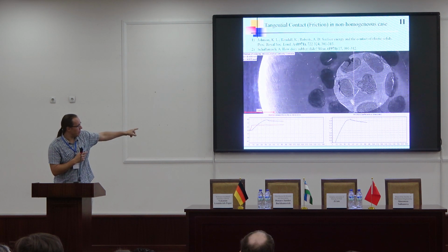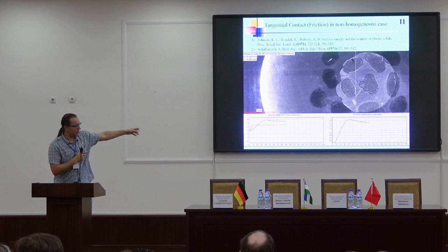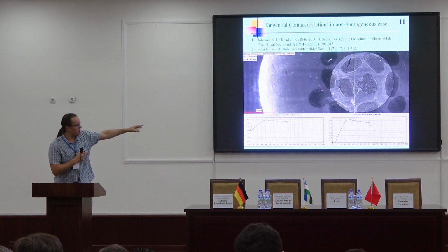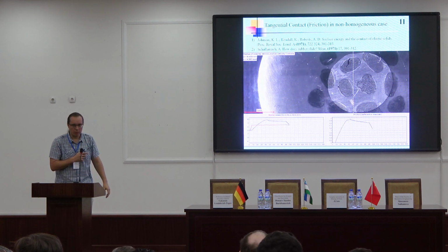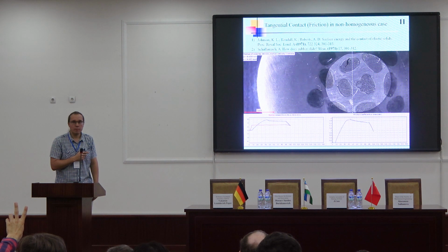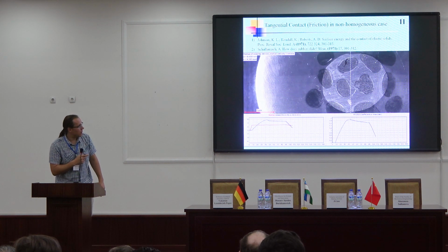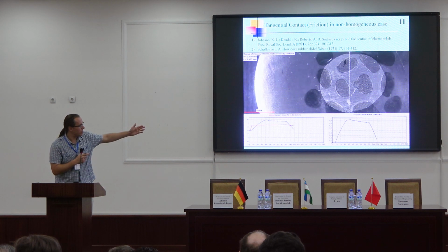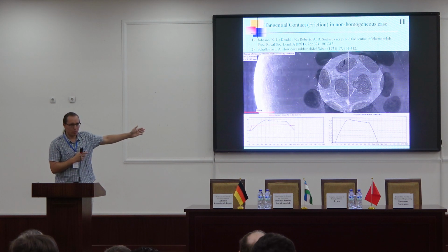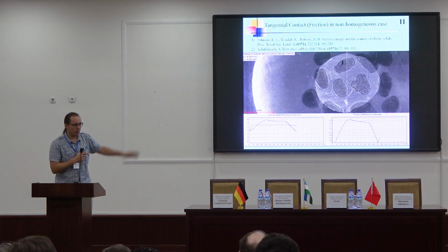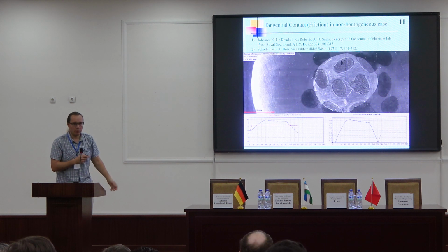Tangential force was 0, then it increased, then something like a stiction spike, and then an approximately constant value of tangential force. And we can calculate here also the dependence of the friction coefficient. Friction coefficient has no physical sense in this case. It can be very big for an adhesive system.